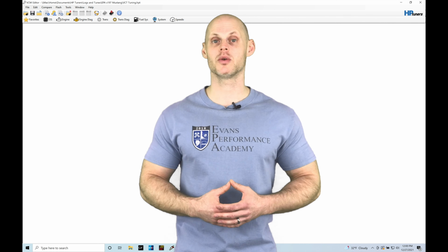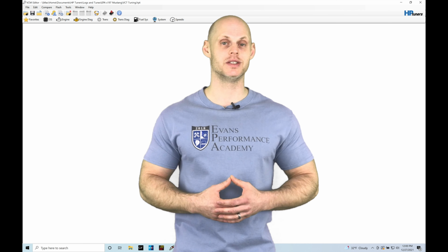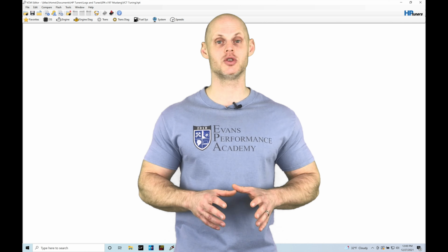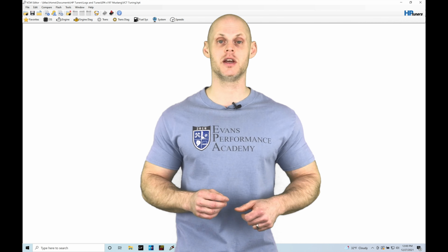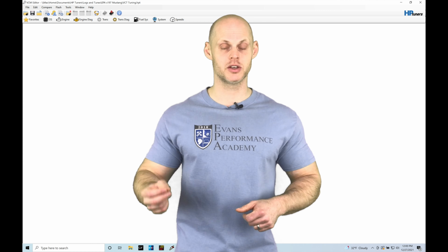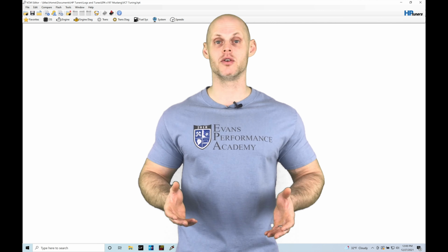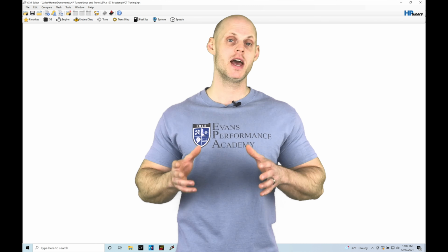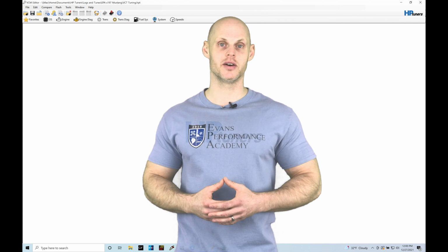In this training module, we're going to take a look at dialing in our idle control within our Gen 1 Coyote engines. Now, we're going to find that the idle control is relatively straightforward to get sorted out, but we need to make sure we're logging specific channels in our VCM scanner and using specific histograms to repopulate our idle control tables. I'm going to go over the basics of idle control and then using our log data to be able to make appropriate changes in our idle control routine. Without further wait, let's jump in so we can check this out.